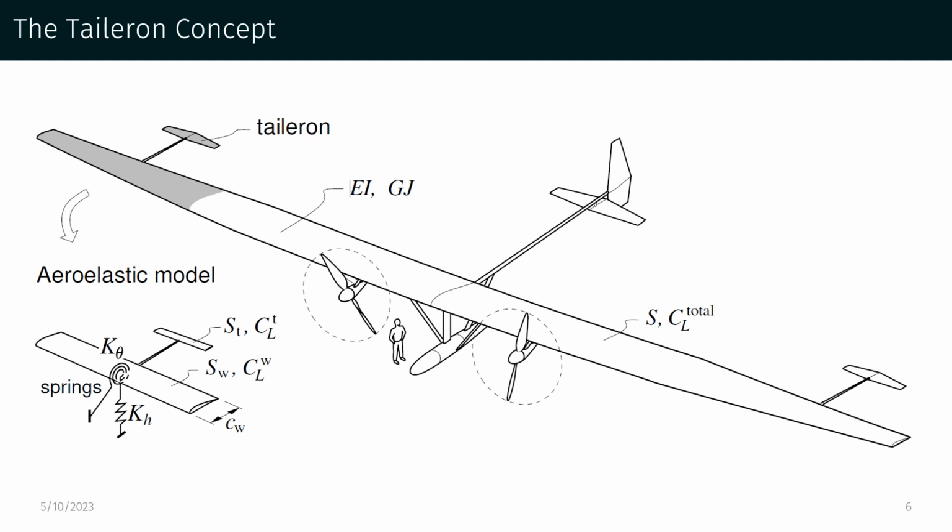Interestingly, the added structural mass of a taileron and its boom is actually minimal. So for example, in the Dawn 1 airplane as built, the taileron and boom subassembly represents less than 3% of the overall wing weight, not to mention the airplane weight. The weight gain of adding tailerons is comparable to, and sometimes even less than the weight gain from adding similarly sized ailerons, because the increased structure in the wing for the ailerons to carry the hinge loads is less efficient than the direct transfer of the loads that can be accomplished through a dedicated boom.